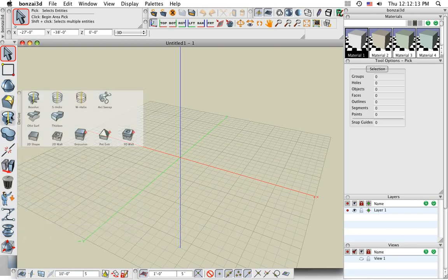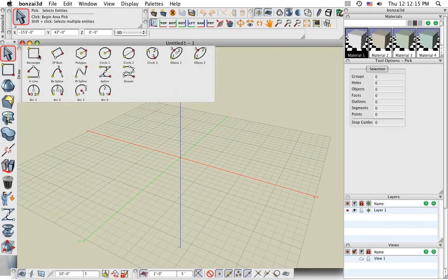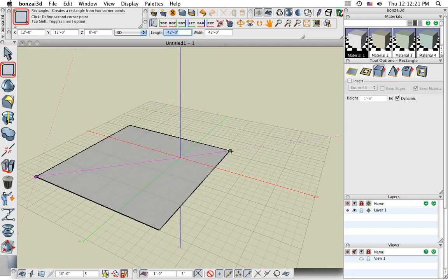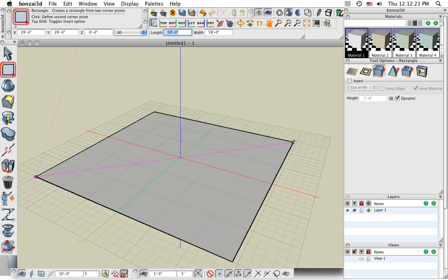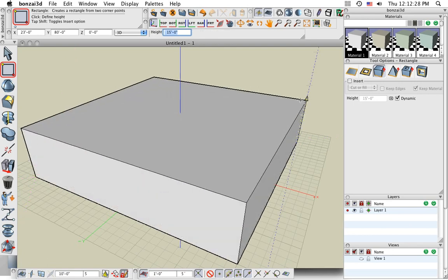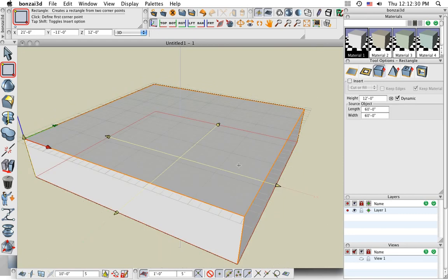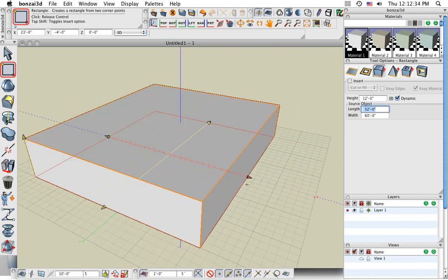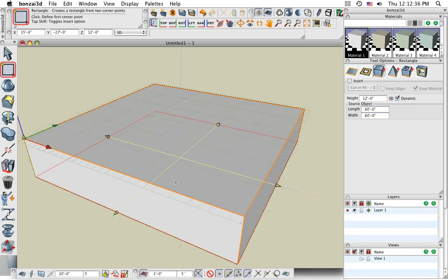Here's all of our modeling tools. If you want to draw something, here's all of our drawing tools. Let's select the 2D rectangle, and notice when I draw that shape, we get these guides that automatically show up. So you can see I can maybe snap right on the guide to make sure it's a square and pull it up. And once we create an object, we get a set of controls. No matter what the object is, we'll get these arrows. And so if you don't quite draw it right the first time, we get these arrows that can move and modify based on what that shape is.